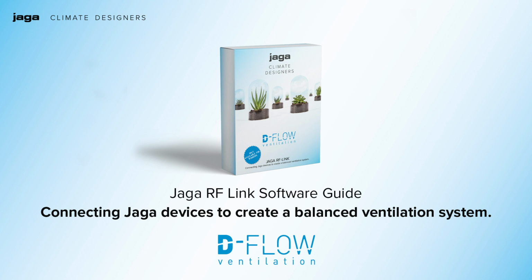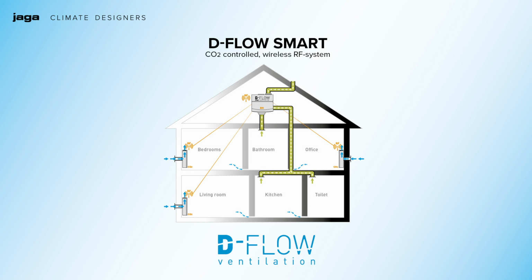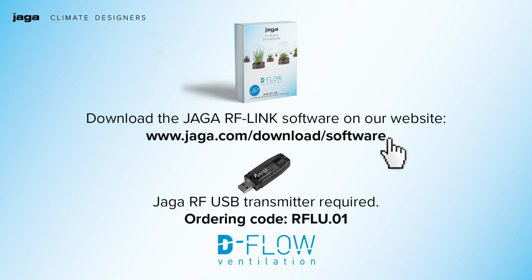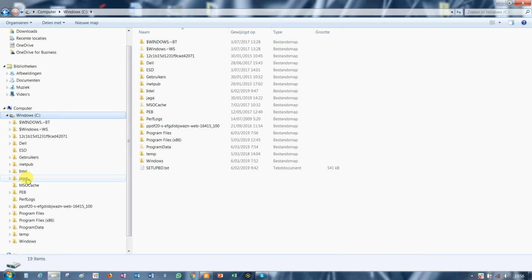Today we're going to show you how to set up your RF link for your oxygen ventilation system. So firstly we need to open up our Windows Explorer and browse to our C drive. Within the C drive you will find the Jaga directory, assuming the software has been installed correctly.